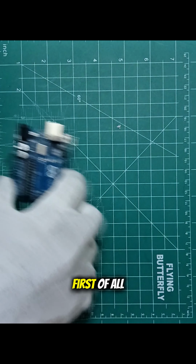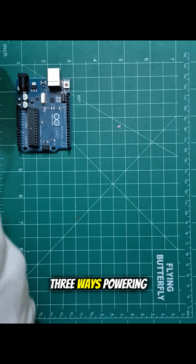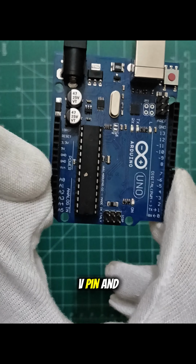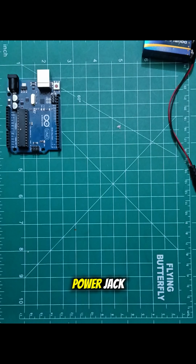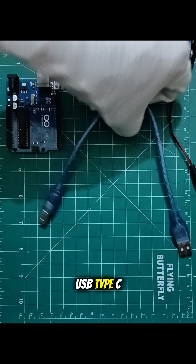Time to make a simple project using this Arduino. Let's go. First of all, we need to power this Arduino, and there are three ways of powering it. The number one way is using the V input pin and a ground pin, providing a voltage difference there, or using a power jack which is at the end of this Arduino. While the last and most common method is using this USB Type-C cable.